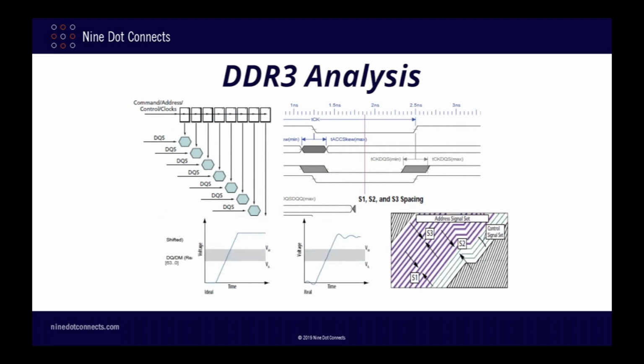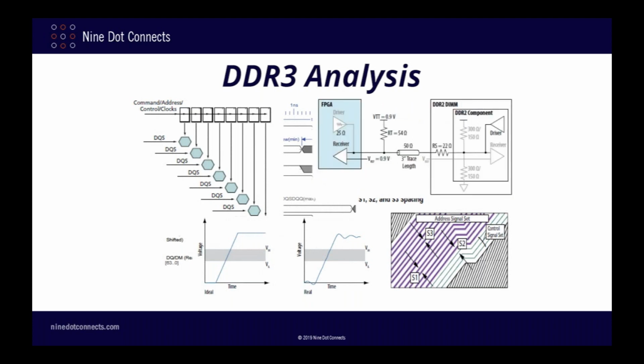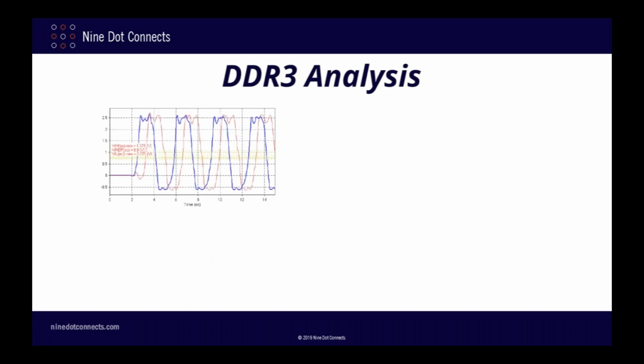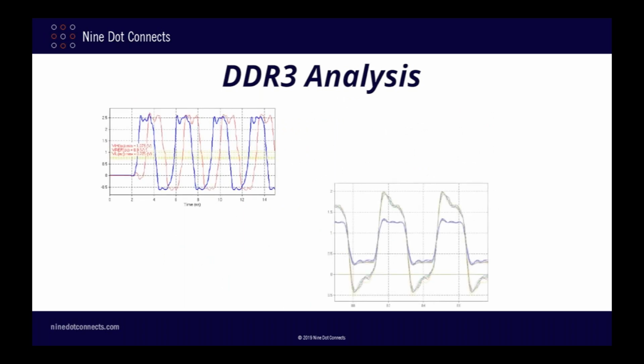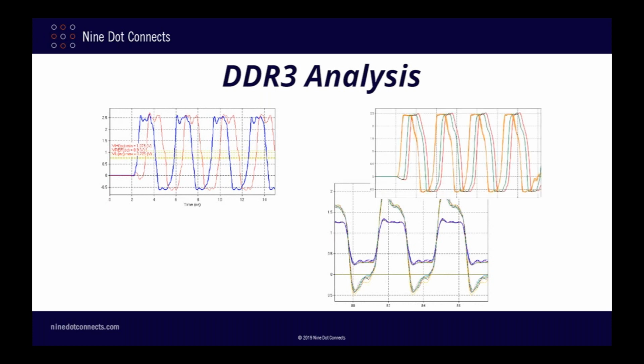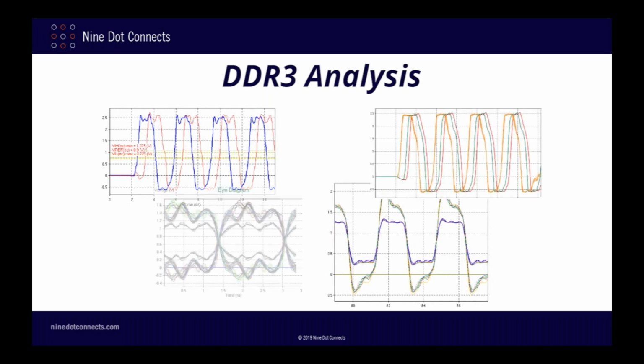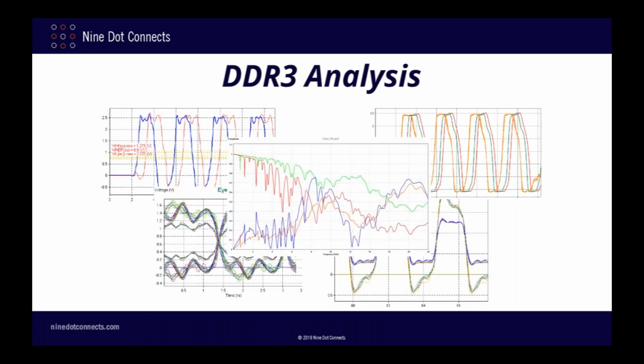When analyzing the operation of the entire DDR3 design, I will therefore move the focus out of the frequency domain for the most part and instead use time domain analysis as my means of comparing various test cases. However, when I start looking at individual elements within the DDR3 design, I may revert back to the frequency domain and present S parameter data as well.